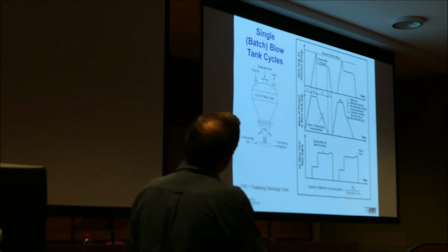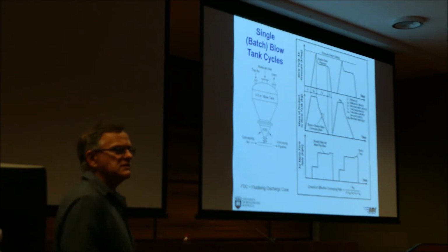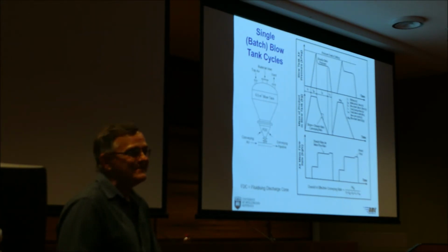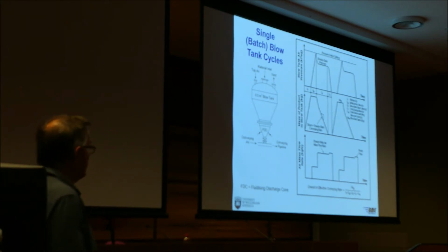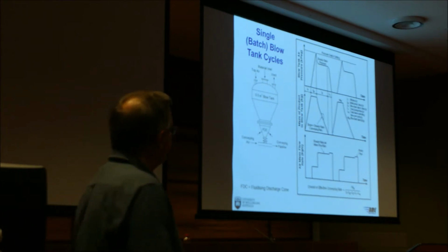And here as well. Some people put a butterfly valve there. If it's cement, it won't last long. Aluminum won't last long at all. Because those valves get chewed out pretty quickly. When they start to leak, you've got problems pretty quickly. So you need the right sort of valves for this sort of service.